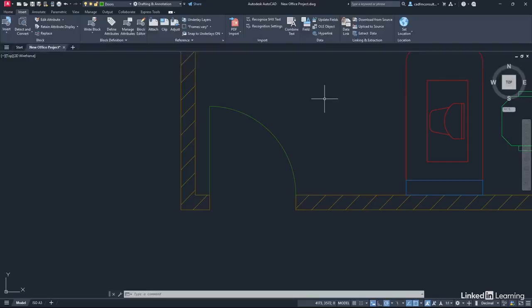We're going to create a separate DWG file of some objects that we've got in our drawing at the moment. We're then going to edit that separate DWG file and redefine a block in the current drawing. Now, you'll remember that we created this block here, the little flippy door. So click on the flip action there, and make sure the door looks like that. Hit escape to deselect. We're now going to go to the write block command.